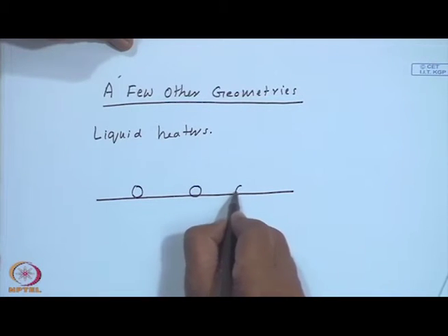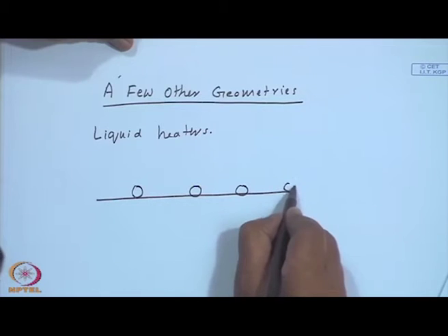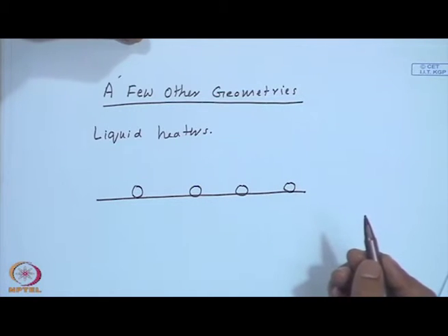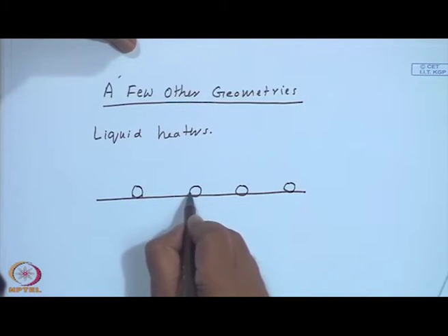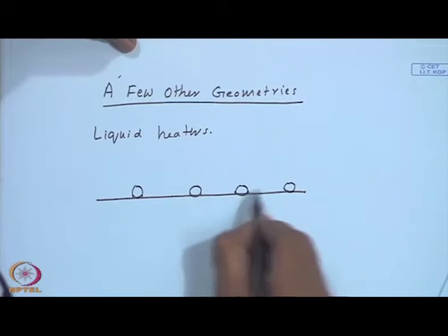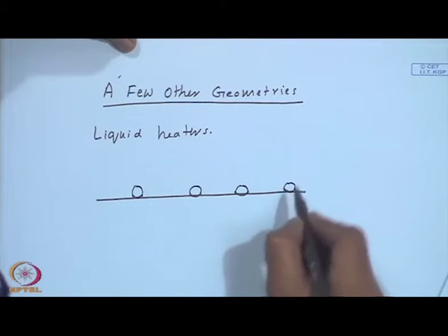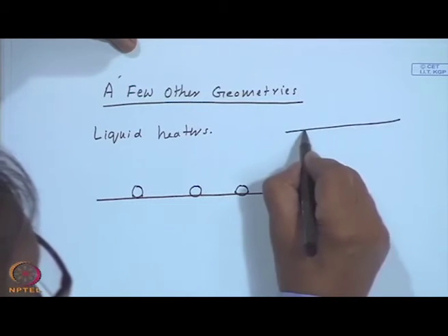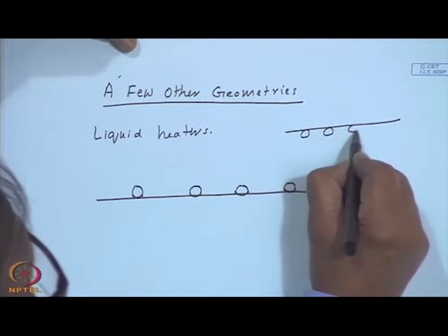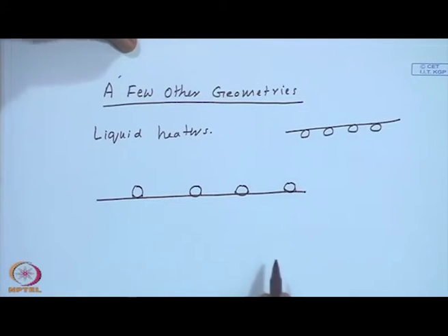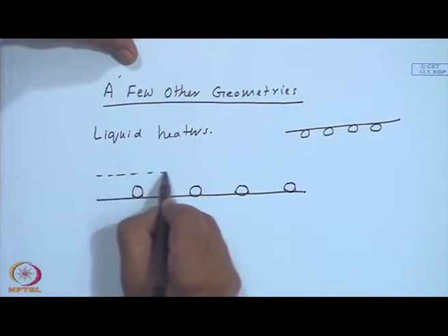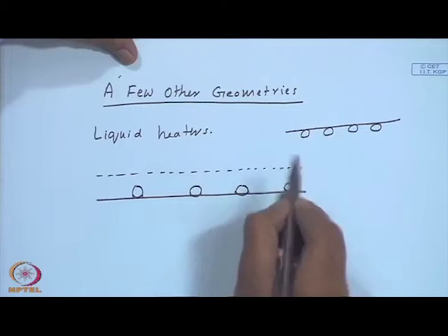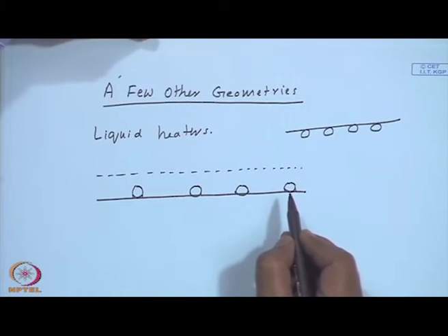Suppose you have an arrangement like this, the absorber with the tubes on the top, soldered or welded with a good bond. Compare this with what we have considered earlier. Some people argue that the tube is directly exposed to the solar radiation, so it will be at a higher temperature, thereby making it more efficient, but others may say that it will also directly lose heat by radiation.